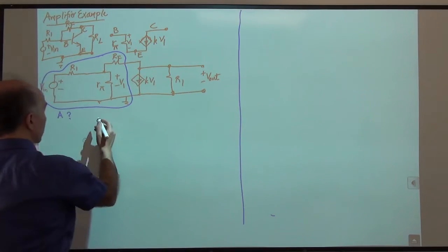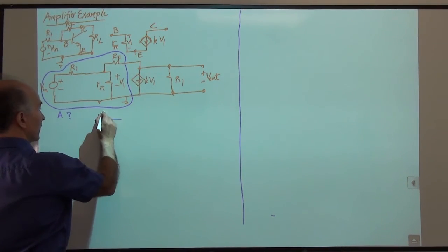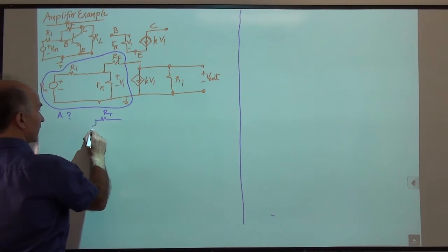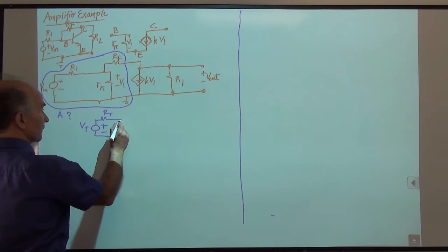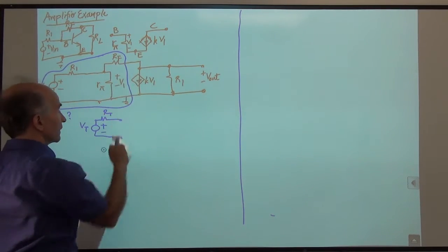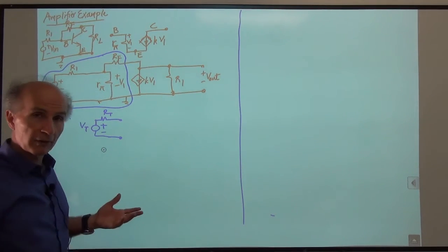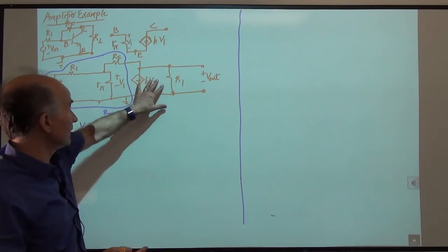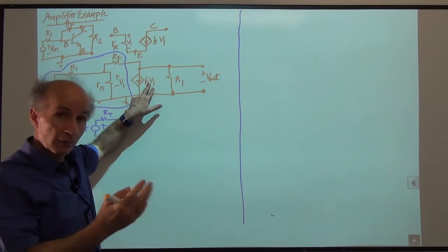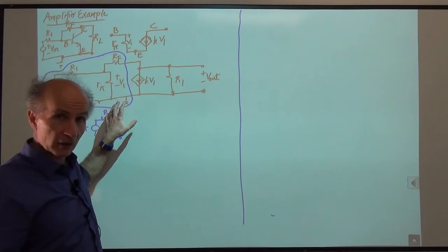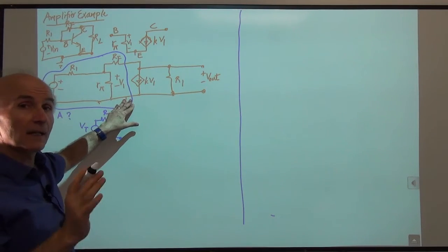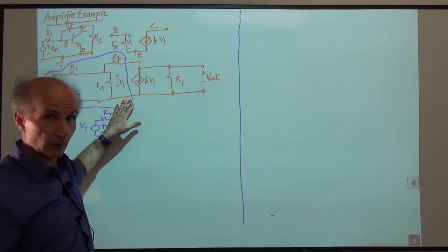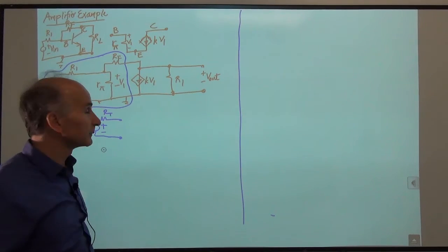So if you build a Thevenin equivalent, it will be like this: RT and VT. All right, that would be these two wires here. Where is V1? We don't have V1. So when I connect this to this side, I have a problem because this needs to find V1, needs to look at V1, but that's gone. So this selection of section A is not useful. It doesn't get us anywhere. All right, so let's throw that away.